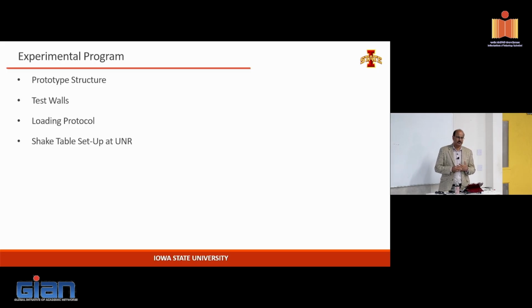We are basically looking at three different types of structure: a cast in place, a single rocking bolt, and the Prevex system. By just comparing the damage pattern or extent of damage, it's hard to tell one is performing better than the other, because we are plastifying different regions and changing energy dissipation. So we had to come up with a different plan in terms of how we would evaluate the performance.